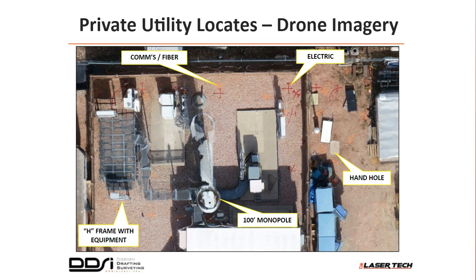And then for our demonstration, the underground utilities located by our partnering private locator are marked in red for electric, orange for the communications or fiber, the comms, blue for water, yellow for gas, and green for sewer. And then we typically have our drafters add these locates right from the imagery, especially of a clear view from the sky, but what if you can't see your assets?